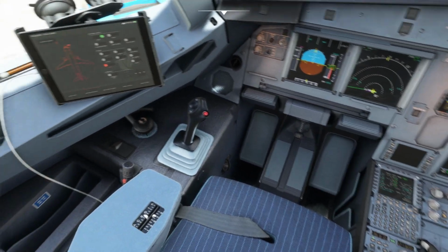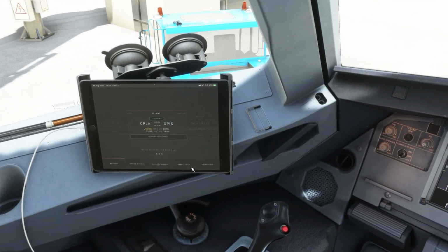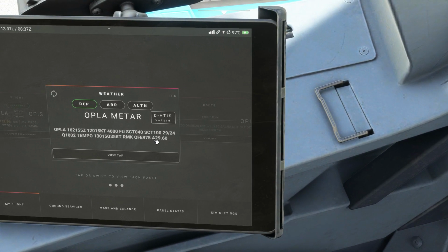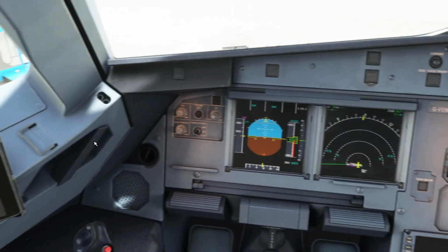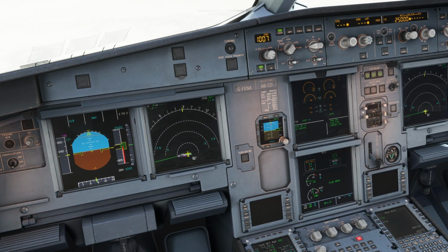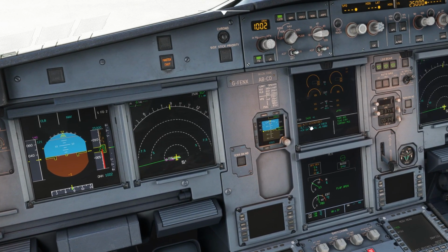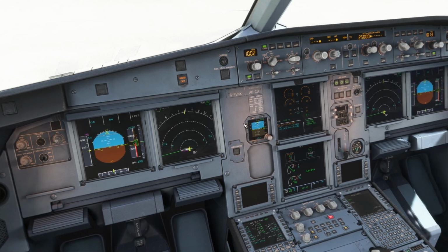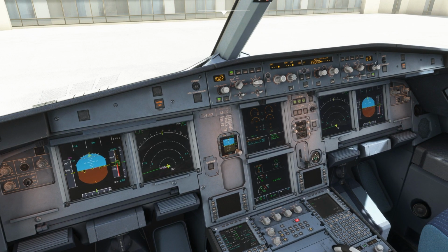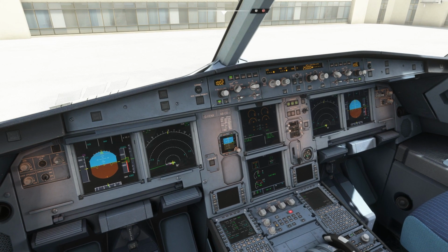And plus the QNH, let's go and get the QNH. It's 1002. So it's 1002. In the fly-by-wire Airbus A320 and the default Airbus A320, it is actually what is the caution? Nav discrepancy. You can see this discrepancy is coming because you have to set this barometric pressure on both sides, for the captain and for the co-pilot. So that's why this error comes.